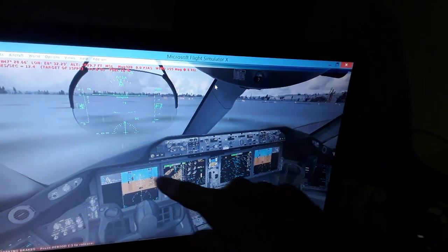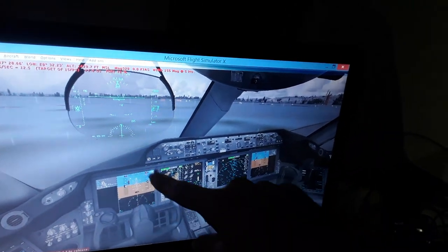We have the horizontal and vertical profile, the flight management, and the primary flight display over here with the HSI and the flight mode announcer. You will see in the navigation display we have also the display of other aircraft that fly around our own aircraft, using the transponder, which transmits a radio frequency to other aircraft and air traffic control and receives from other aircraft. You can calculate, using the radio frequency and its computer, where the other aircraft is located, its distance from our aircraft, the altitude difference in hundreds and thousands of feet, how many feet it is above or below us, and also whether the other aircraft is climbing or descending.